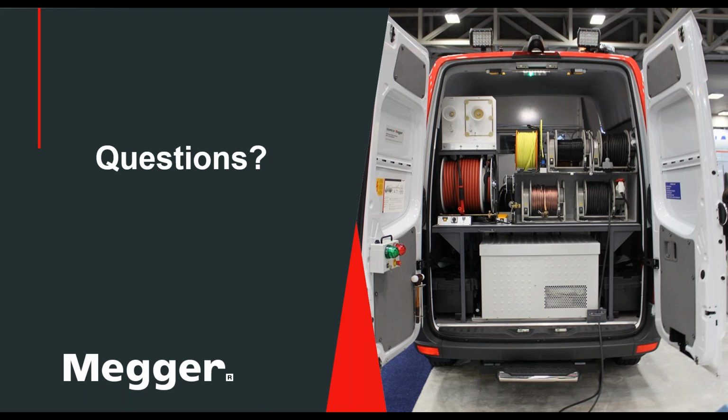And then, of course, you don't know unless you perhaps repair that fault, and then you do a quick verification high pot test to make sure there's not a second fault. You won't know that second fault is there until you try to re-energize.